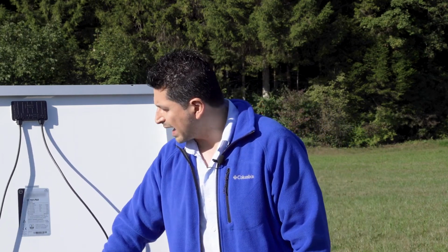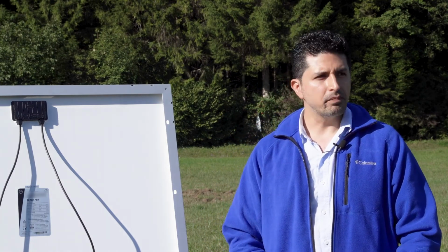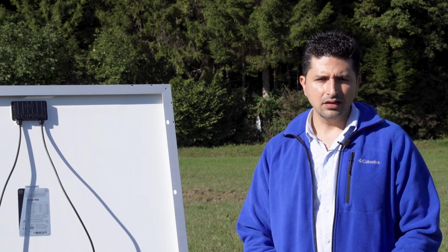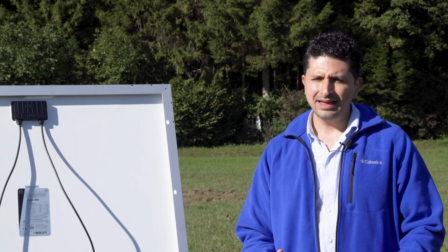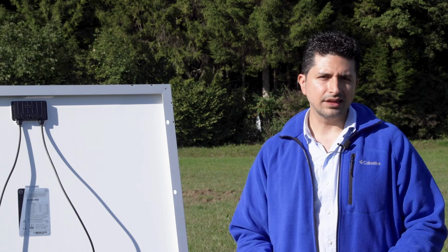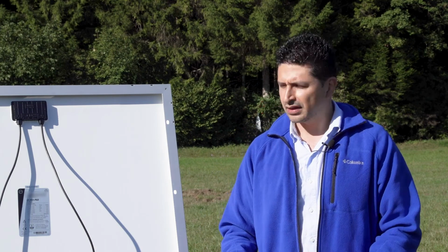These two values are really important for us to understand whenever we are going to connect electrical equipment. The open circuit voltage is important because we never want to exceed the input voltage which goes into one system. So the voltage that we will use whenever we are going to do our estimations will be the open circuit voltage.